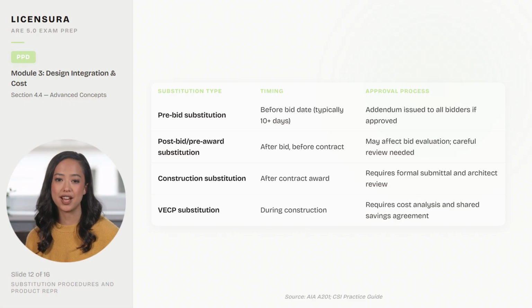Code compliance, including occupancy, construction type, egress, and accessibility. Structural architectural coordination for grid alignment and clearances. MEP architectural coordination for equipment rooms, plenum space, and access panels. Building envelope integrity, including air barrier continuity, thermal bridging, and moisture management. Life safety coverage for sprinklers, fire-rated assemblies, and smoke barriers. Specification drawing consistency through cross-referencing key details. Sustainability compliance for energy codes and LEED credit documentation.